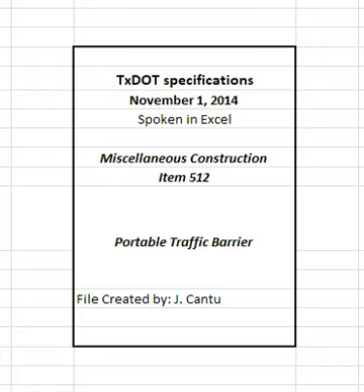Table 1. Precast barrier tolerances. See table in specifications. Install the barrier sections in accordance with the details shown on the plans or as directed. After use, stockpile barrier sections and connection hardware that are to be retained by the department at the location shown on the plans or as otherwise directed.